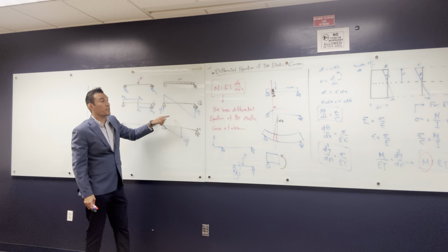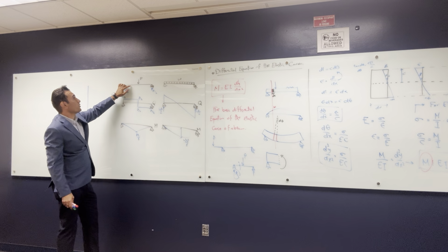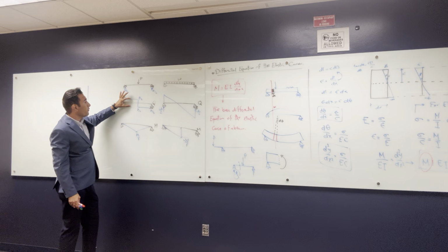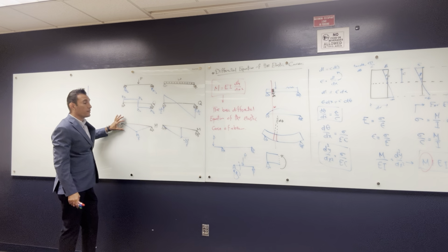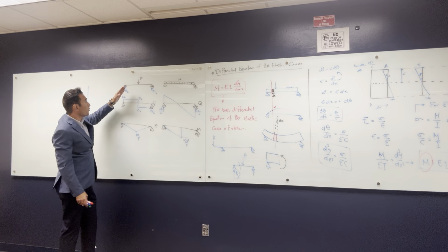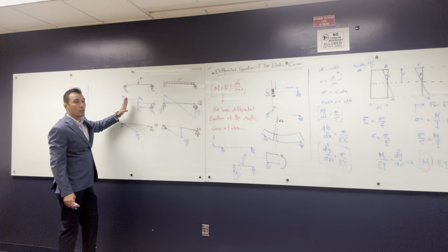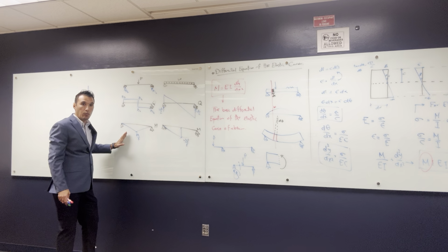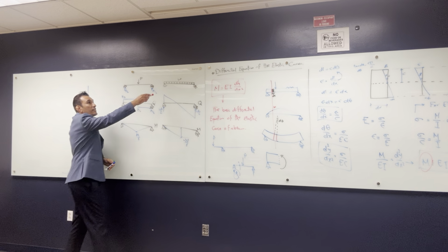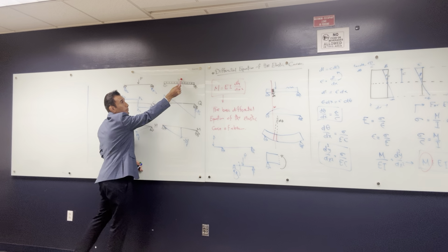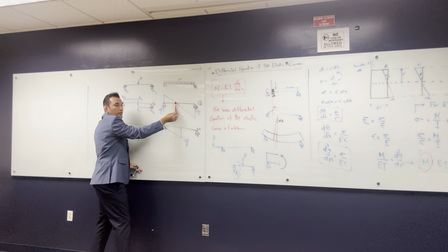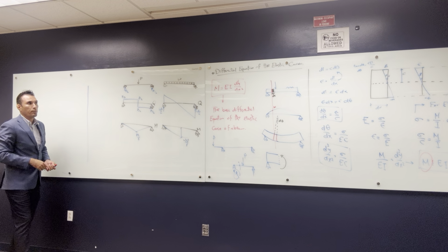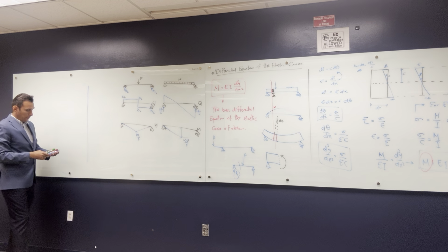So it increases in degree. Here there is no load, there is 0 load, and then the shear starts to become constant, and then the moment starts to be linear. So you move from 0 load to constant shear to first degree bending moment. So it increases in degree. W constant, the shear linear, and then the moment. So there's definitely a relationship between them. Let's find out.